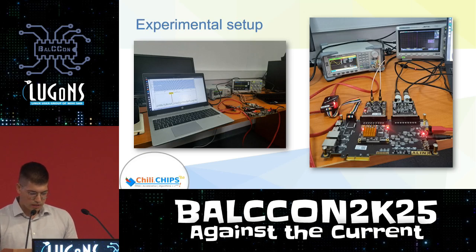This is all connected via UART to our laptop, as you can see on the left picture. And on the screen you can see a Python script we have written to reconstruct signals from those samples and do a fast Fourier transformation to give us a frequency spectrum of the sampled signal.